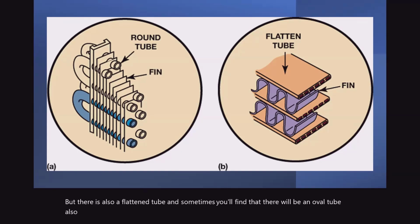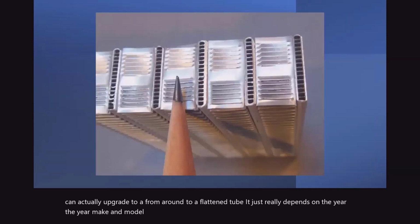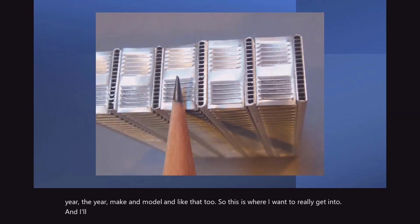So it depends on what kind of system and what the manufacturer put in. Sometimes you can actually upgrade from a round tube to a flattened tube. It just really depends on the year, make, and model. This is where I want to really get in, and I'll go deeper into it when we get into just condensers, a little segment on that.